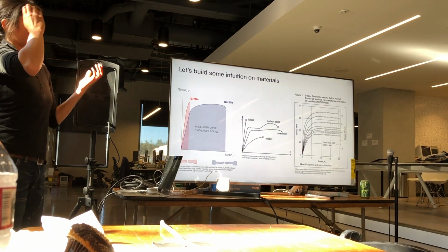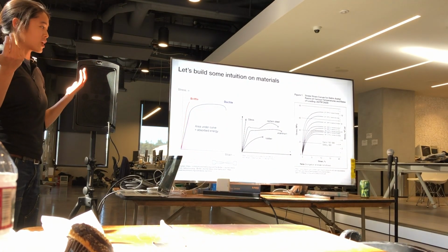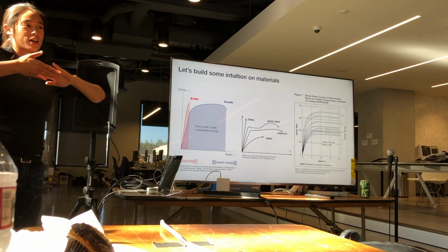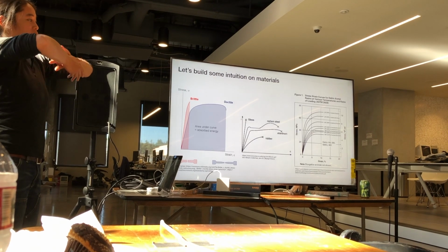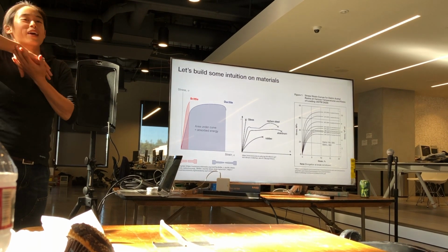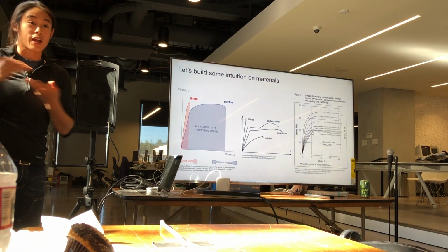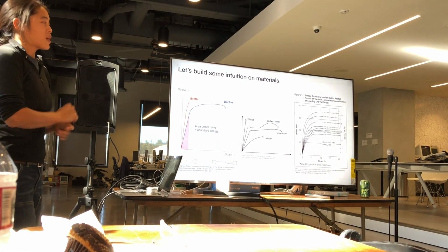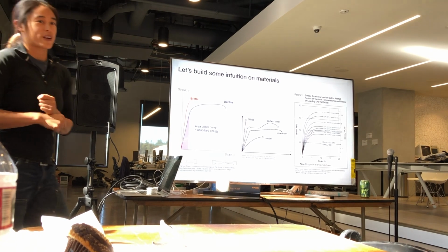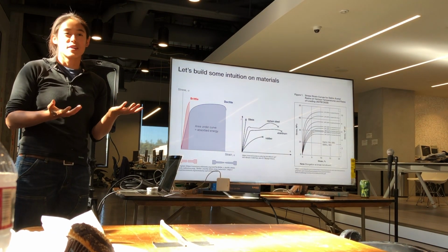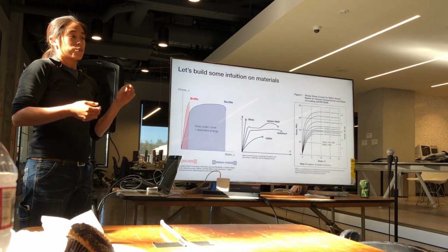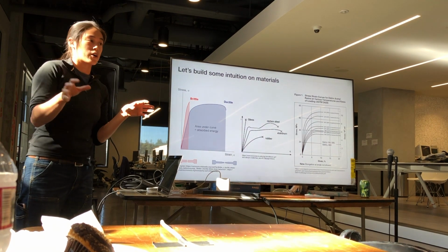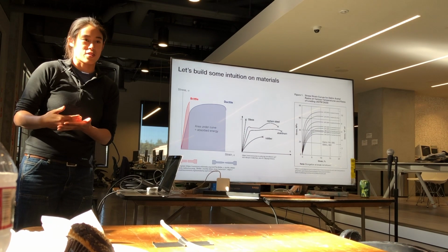Plastics are long polymer chains that are weakly bonded together, so as you stress them apart, they're sort of like wet spaghetti. They might actually pull apart from each other and then stay in that shape and not really want to come back. So plastic, you might have already heard, will creep. Creeping is when plastic is sustaining a force for some prolonged period of time, and then it sets into that shape.